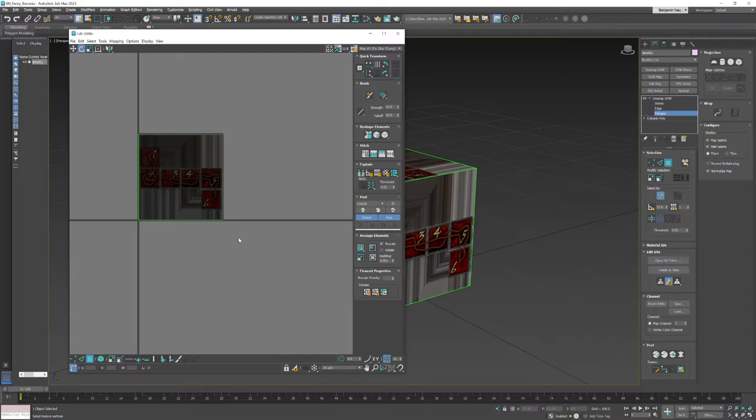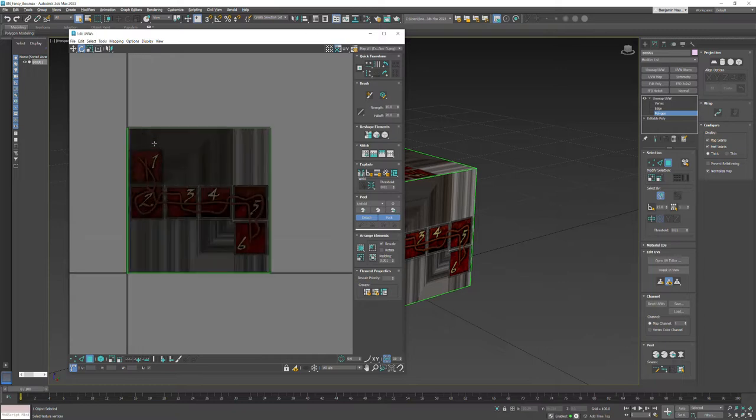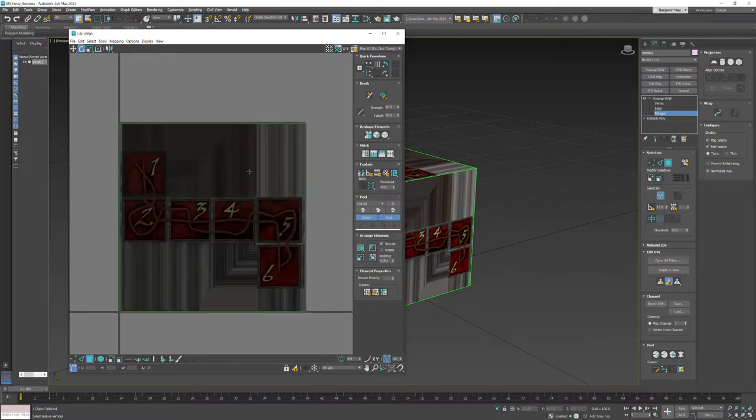Because a lot of UV mapping is image-based, projected on it. There's a lot of cases where you're going to have, like I said, explicit mapping, which is a custom UV set, like we're dealing with here. Everything's going to happen inside a 0 to 1 custom space. Doesn't always, there's lots of cases where it doesn't, but this is a good way to give you a sense and an anchor. This is your basic coordinate system you're working in. So let's do mapping, flatten mapping, and say okay.